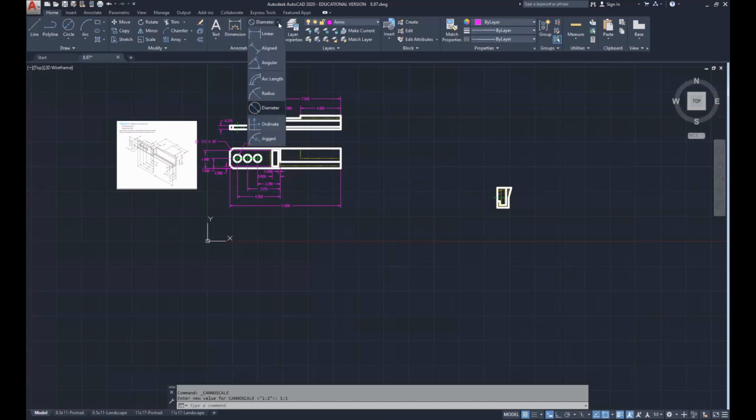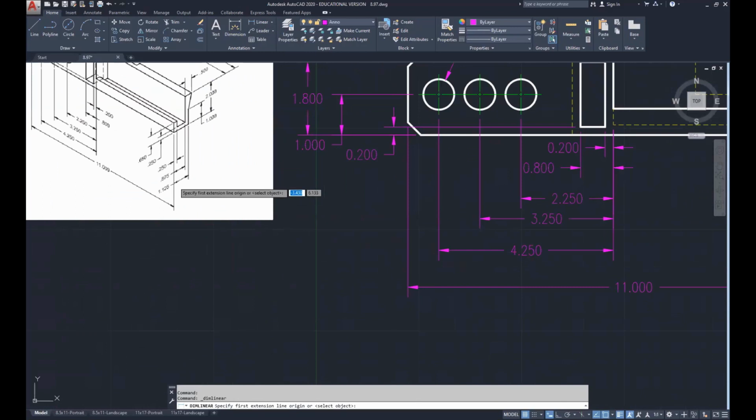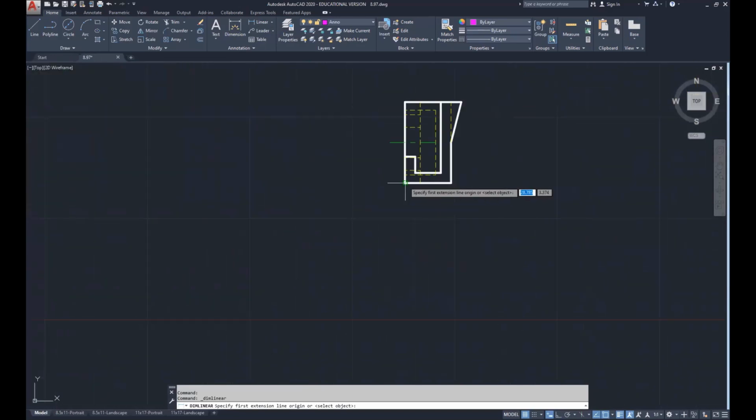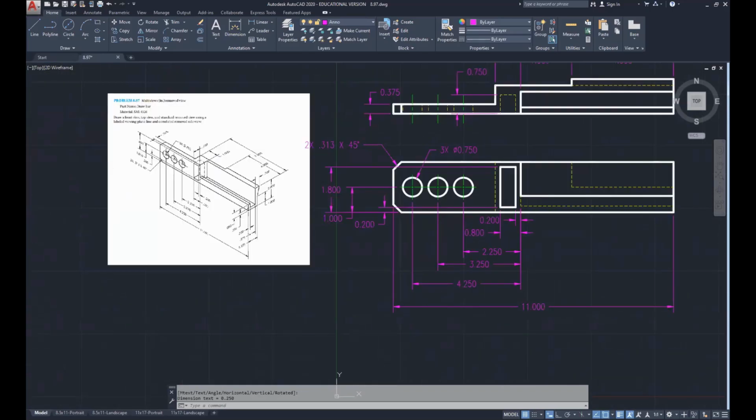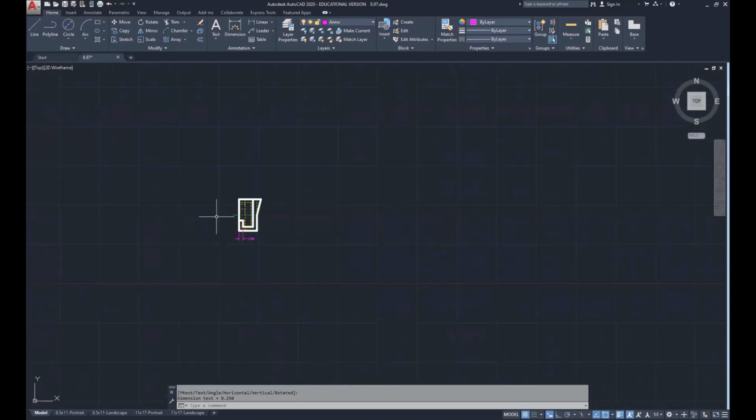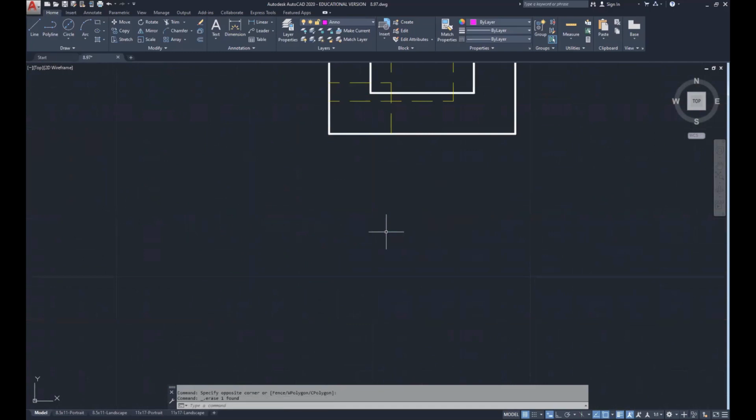And we'll place a linear dimension. Let's go ahead and dimension from here to there. And you can see that this dimension is a little bit smaller than this dimension. But because this drawing overall is going to be 2 times bigger than this drawing, the dimension style needs to be a little bit smaller. Is it pointing in the right direction? Let's bring it out. So we're going to select this dimension, hit delete, and we're going to go ahead and put it back in. But this time we're going to go from our right to our left and place that dimension accordingly.